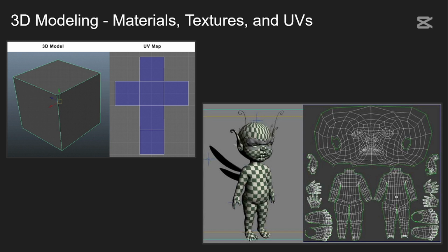And so this 2D representation of that 3D skin is called a UV map. It's called UV because those are the coordinates, instead of X and Y, so that you don't get confused with X and Y coordinates on a 3D model. It uses U and V. U is one dimension, V is the other dimension. And so you need to get a sense for how your 3D model might unwrap and how the texture will then be applied to it.